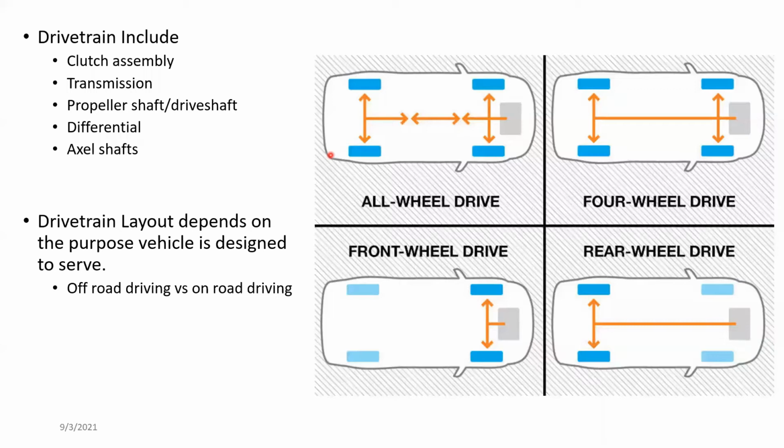And four-wheel drive and all-wheel drive. There's a difference between these two. The main difference, I think I have already discussed, is that in four-wheel drive the power will be transmitted up to all four wheels. It can deliver power to the front and rear wheels when you choose it. So you have to select whether to go on four-wheel drive or drive as a two-wheel drive. That's the difference in four-wheel drive.